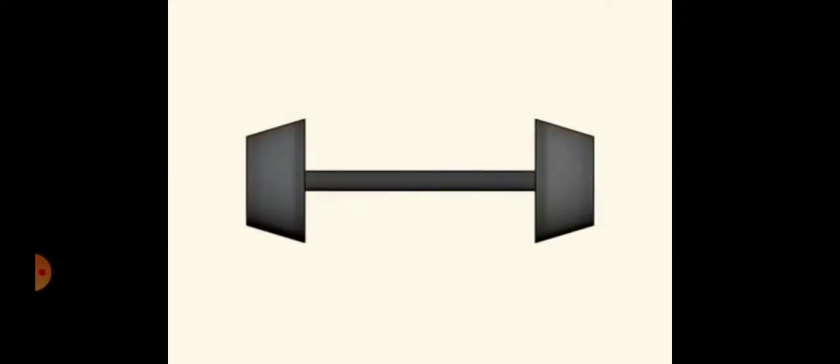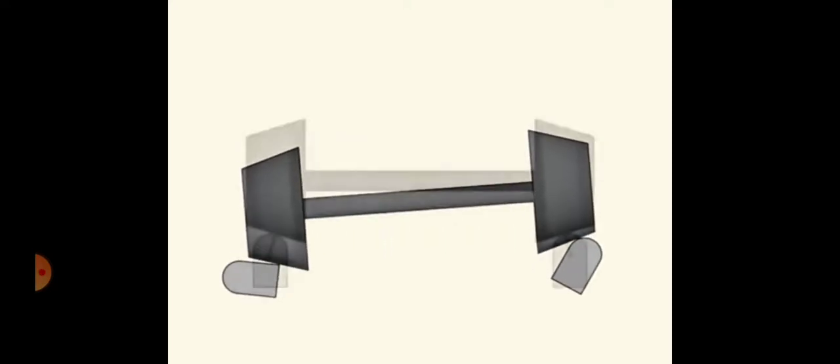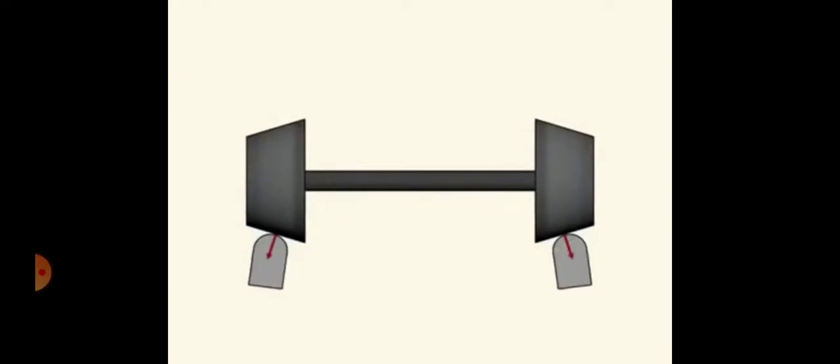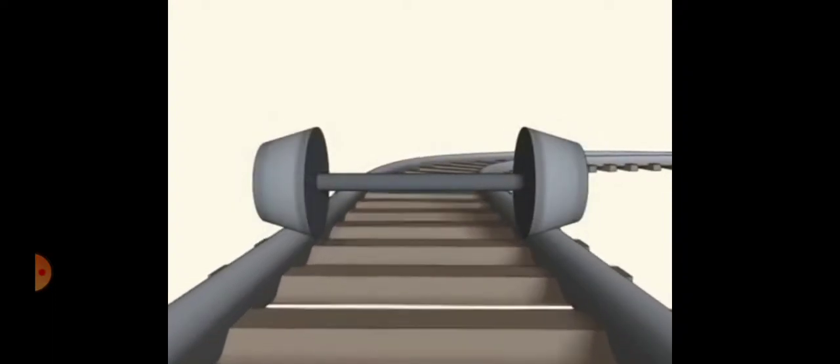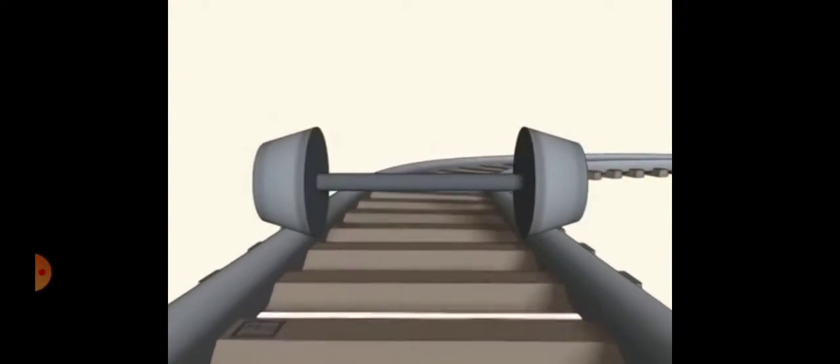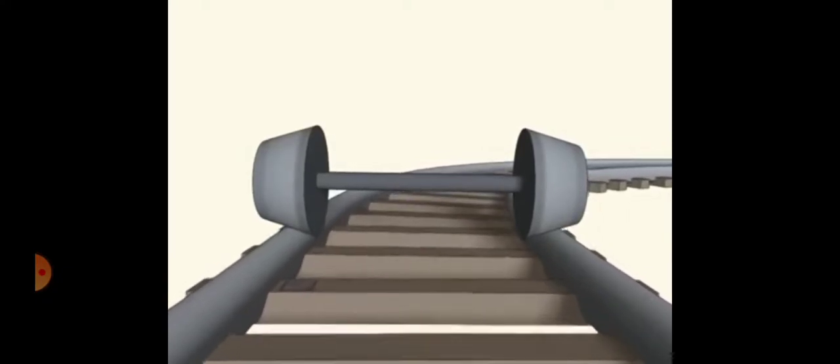So this is the wheel. It is provided in cone shape. The lower part is the rail, and if it is provided straight without a cone, failure will occur. So for that, the wheels are also provided a slope of 1 in 20. Okay, so this is how the wheels are moving on a track.